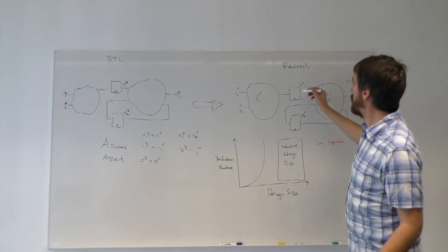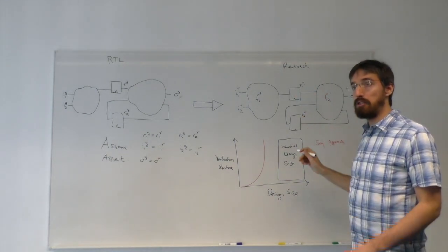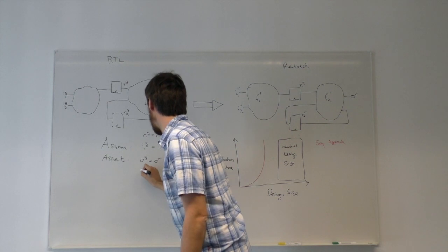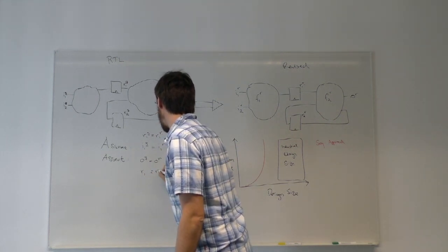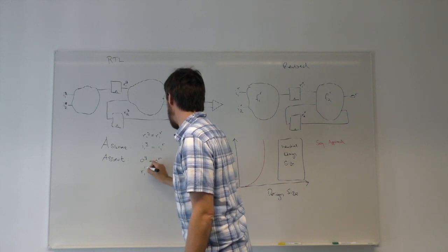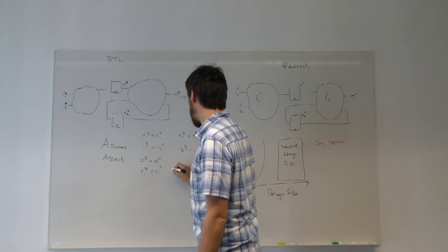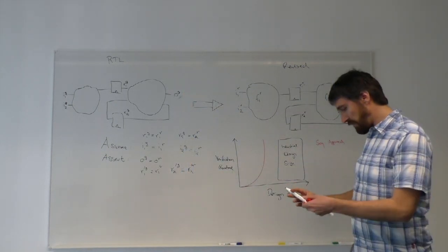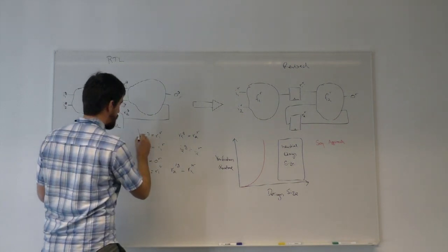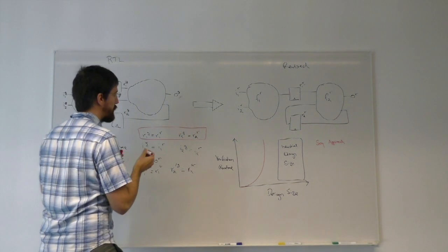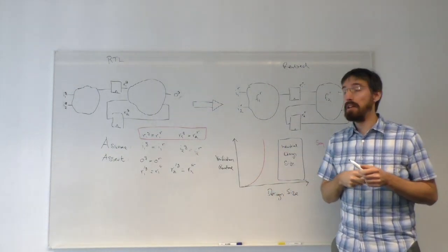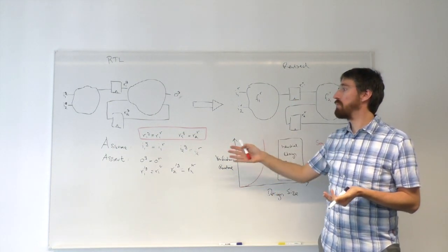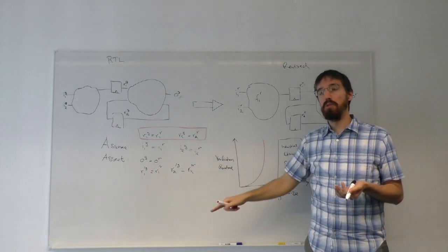The way you would do this here is that at the inputs of the flops, the next state values need to be proven to be equivalent at all times. So this adds additional assertions here. The ones you are adding here would be that the next state, which I'm going to indicate with little ticks, on the golden and on the right side are going to be equal, and the same thing for the second flop, R2. So this part here, let's frame that. This is in academia generally referred to as an inductive invariant. It's an inductive invariant because it's always true, so that means it's invariant. It's inductive because assuming this is sufficient to prove it in the next state.